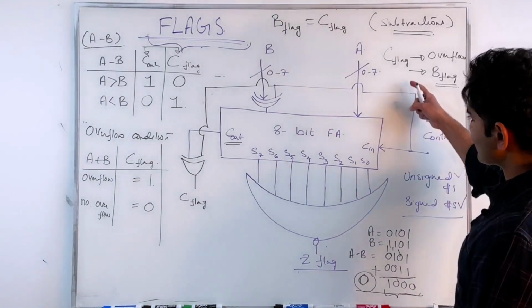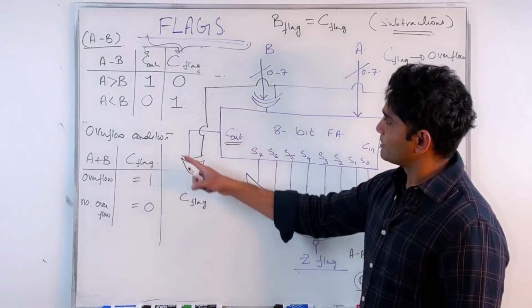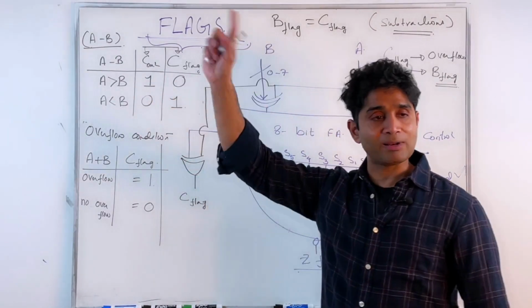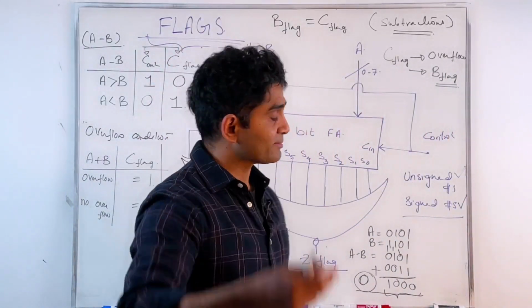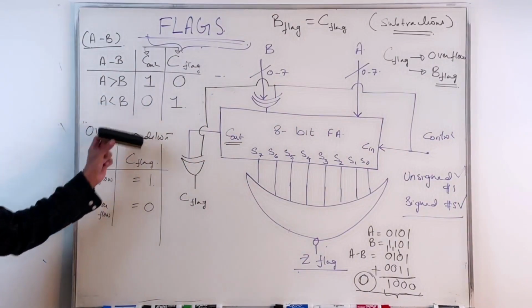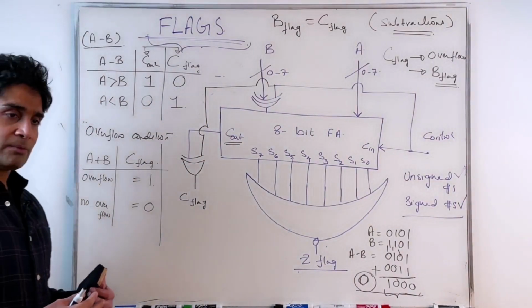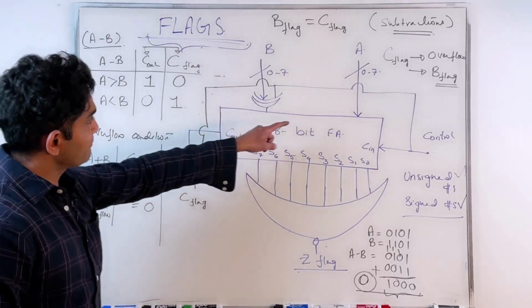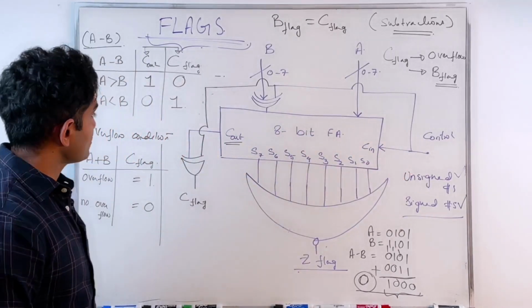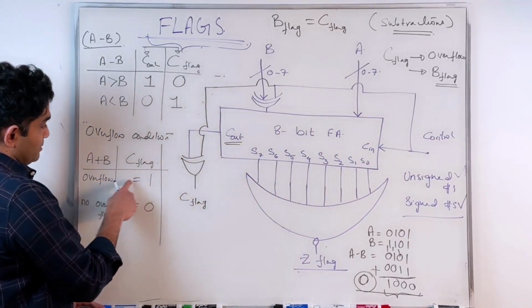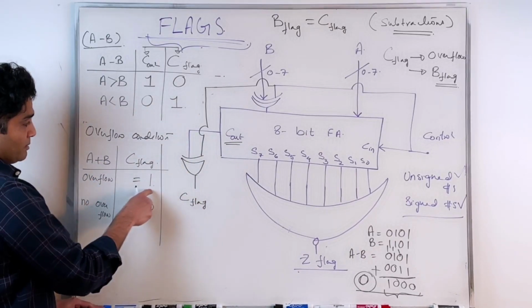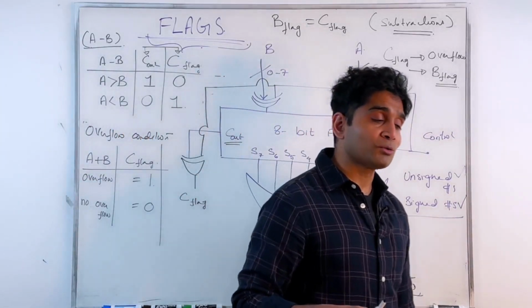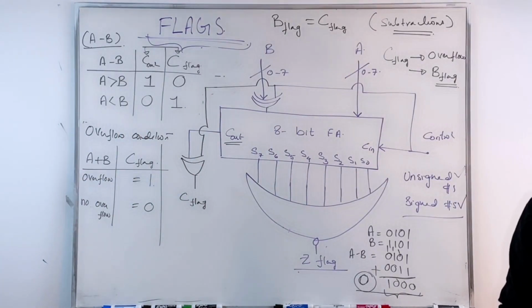Okay, so when I'm doing the subtraction operation, my C flag is the inverted version of cout. Every time I have to borrow, the C flag acts like the borrow flag. The borrow flag is set, consistent now with this. When I'm doing the addition operation and I want to look for overflow, my control is 0, and my C flag is not inverted. So every time I have an overflow and I'm doing the addition operation, my C flag is set; no overflow, C flag is 0. Of course, the overflow condition also works for subtraction operations as well, right?